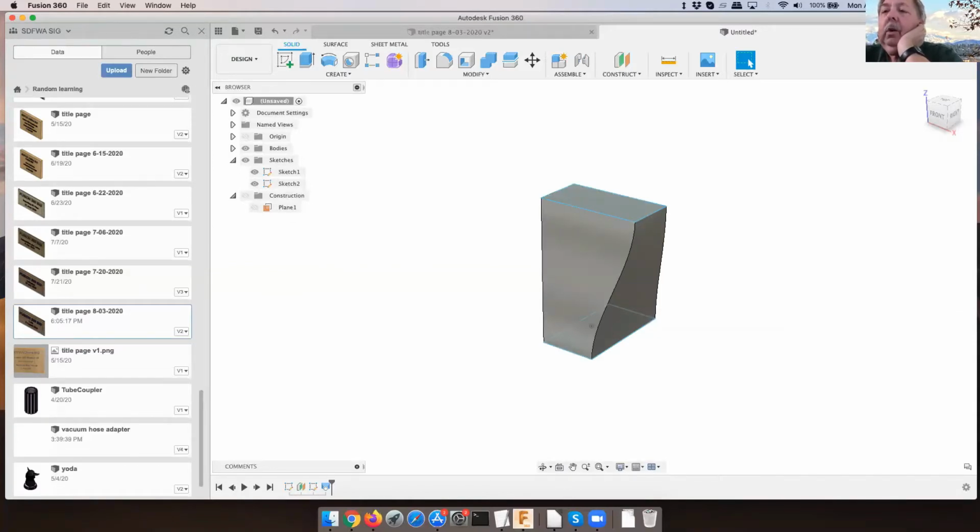If you were to do, like, a duct connection where you have maybe an inch or 2 inches that are straight, and then you have a drop down for a couple inches so you don't get turbulent airflow, and then you go back to the lower side, a reducer, etc. Would you do that with direction and multiple profiles? Yeah, there's a couple of ways to do that, and we'll do something like that later on tonight, because that is a great example to show it with. Right now we're just doing 2 profiles, but we can do multiple profiles.